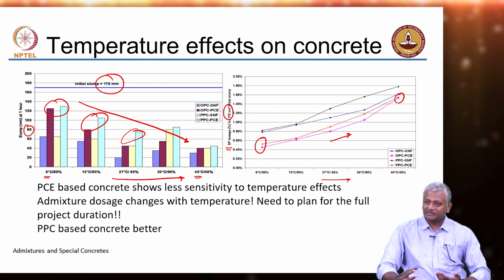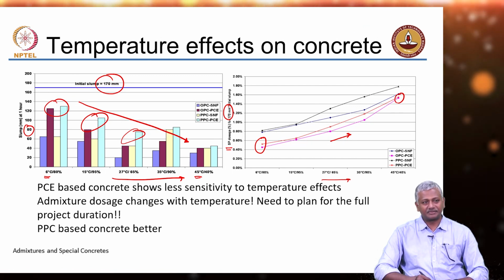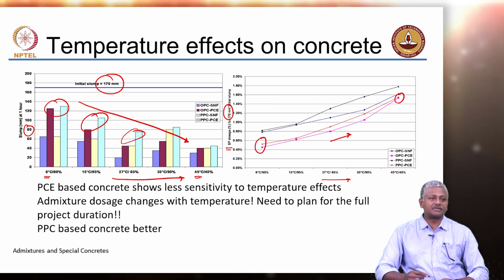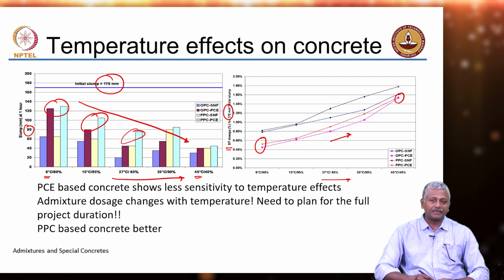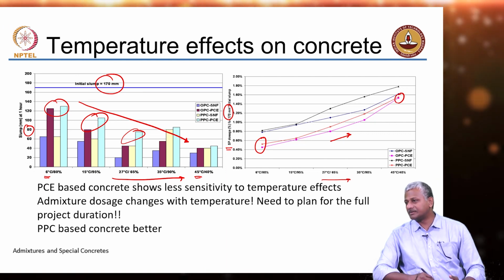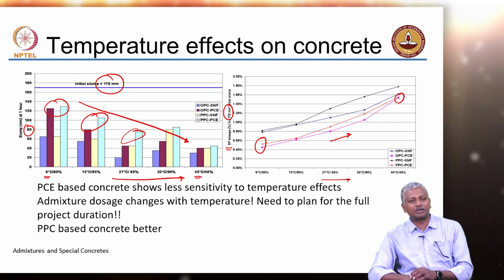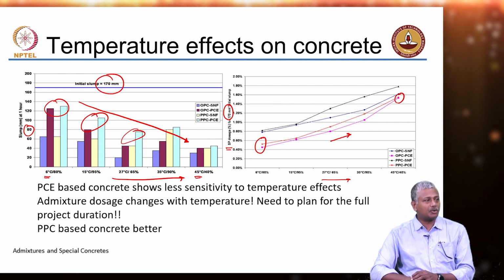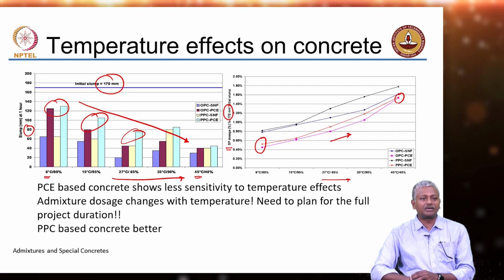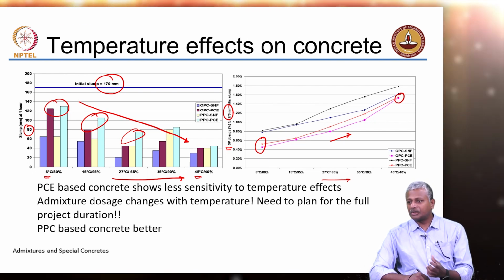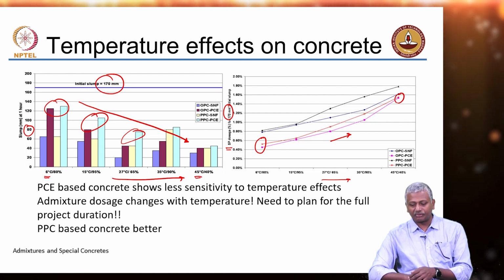Okay. But all of these factors will affect. There was another project in which we were using silica fume as a cement replacement in concrete. It was needed because the requirement of early strength was quite high. It was a precast concrete subjected to steam curing. So, to cut down the cement content, to ensure that we got the required strength, we had to use silica fume. We will talk about silica fume later.